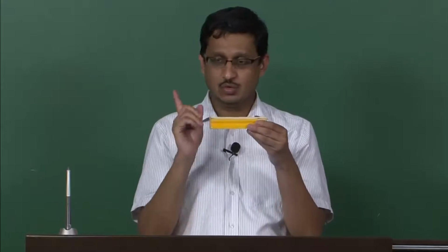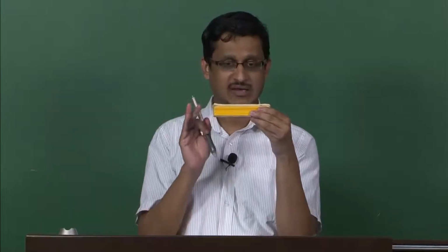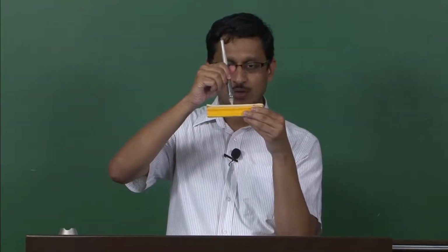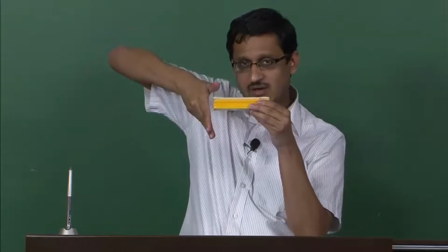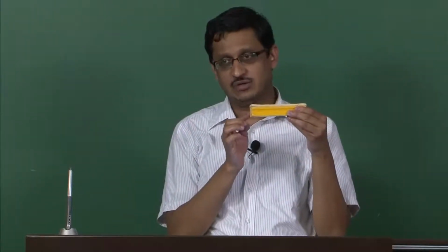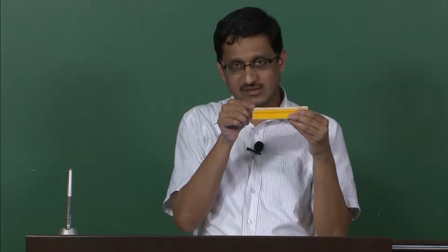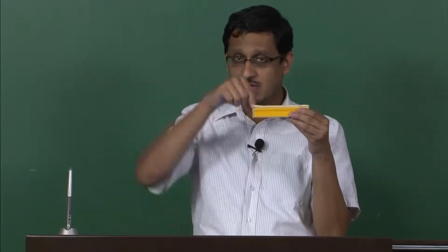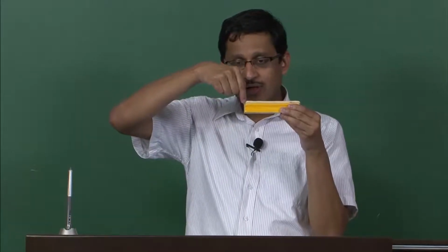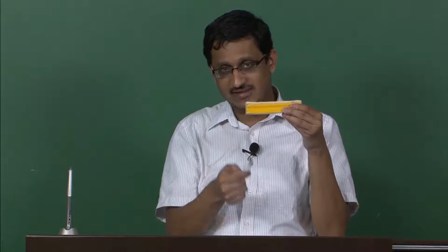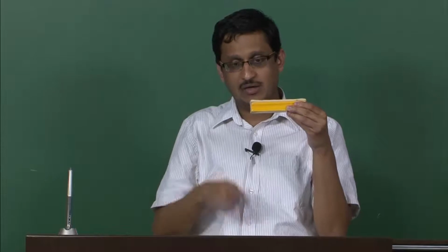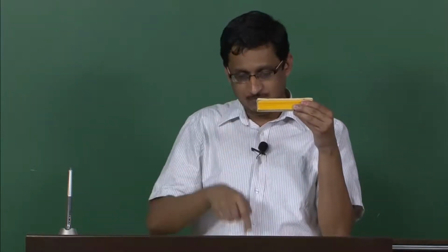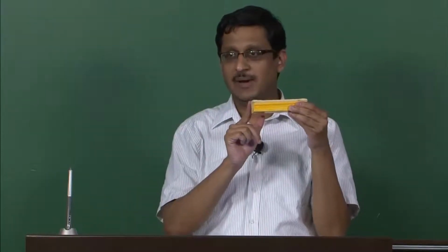Now if I ask you what is the total current that is passing through a particular plane, which I will obtain by cutting through this material in this way. So you have to imagine that I am cutting the material this way and exposing this particular cross section. Okay. Along y I go a certain distance w. So maybe this is y equal to 0 where the point I am showing, this is y equal to w, and then you take this edge, you keep going inside the conducting material, you go all the way to infinity, come back up parallel to this line, and then come back onto this edge to meet back at the surface.